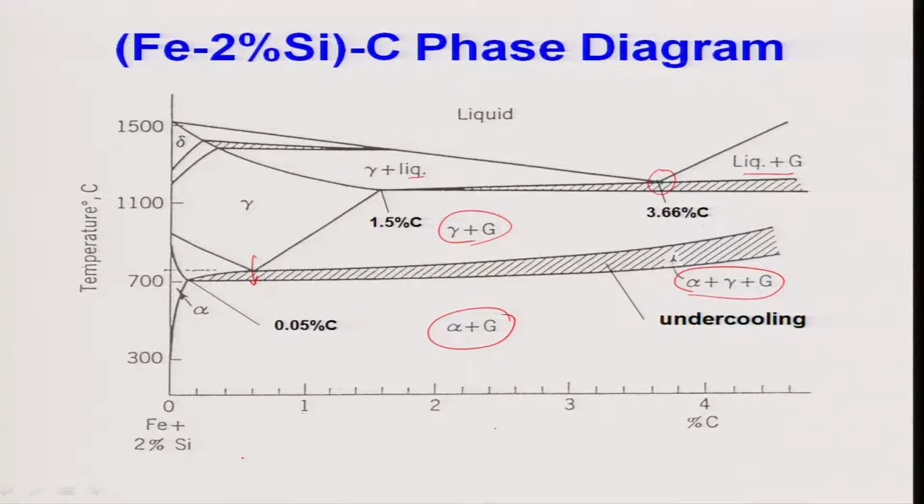It is not pearlite, it does not give you the pearlitic lustre. You can see here this has been calculated and also experimentally verified. This diagram tells you that if you have silicon and the carbon concentration increases in these alloys, the phase formation will happen this way. So, you do not see any field of cementite in this diagram. What you see here, everywhere cementite is replaced by graphite.